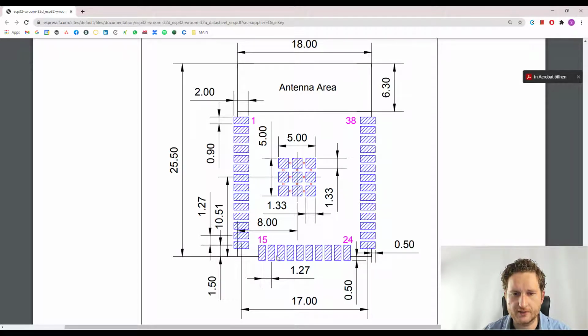So there are 5 pads on each side. So we have 4 times the pitch, and we have to add a half pitch. And in Y, it's 0.5 from the edge. So our middle of the pad must be 0.5 plus.